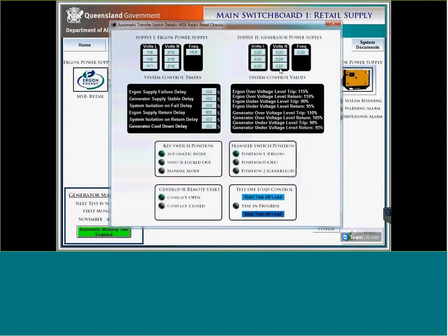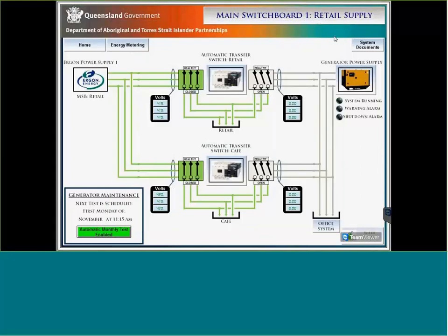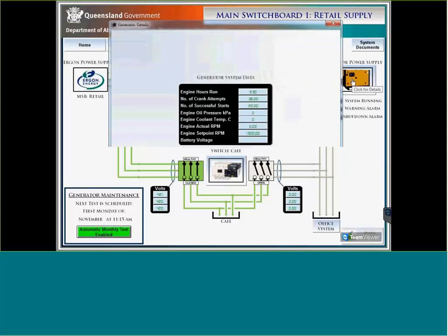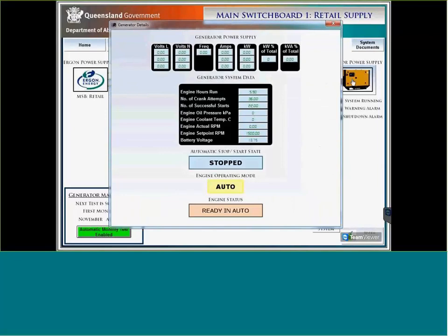Each ATS, again with Modbus RTU, gives us a lot of data where you can remote in under problematic situations and really see the timings and what's happening. We've got the same with the genset. From a service perspective, this was a fantastic feature. We could see how many starts it had, things like oil pressure, coolant temperature, actual RPMs, and what state it's in. That was a must for our customer in that remote location.